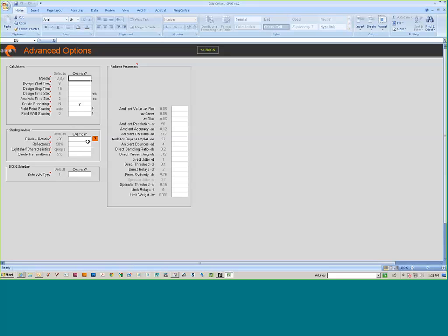Okay. And again, if you have a shade, if you have a Mecho shade or something like that, you can try the shade transmittance, and the default is 5%, but you can change that based on your specs. So again, this is where you would change the shading part of things and go back and redo the calculation and see how shades help you overcome the discomfort glare that you had.